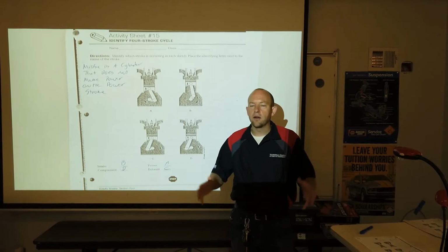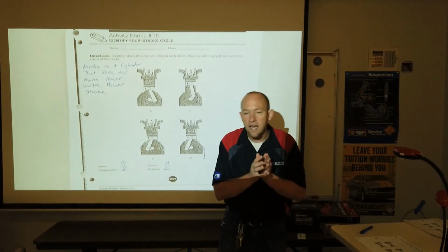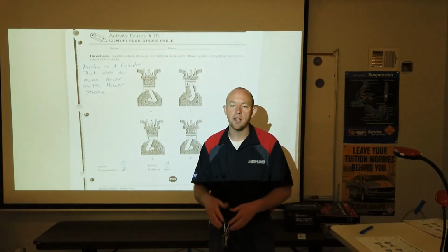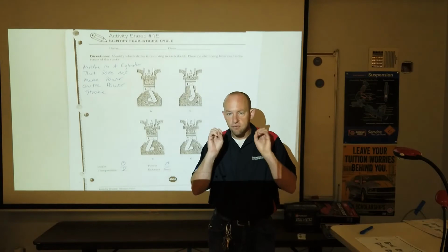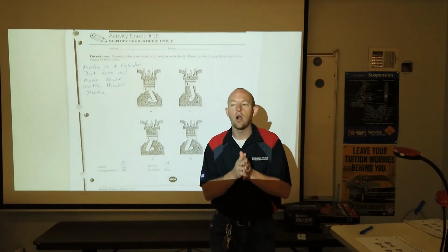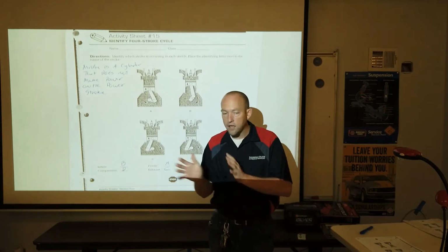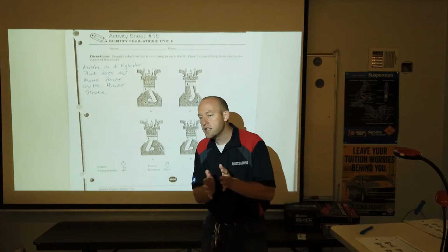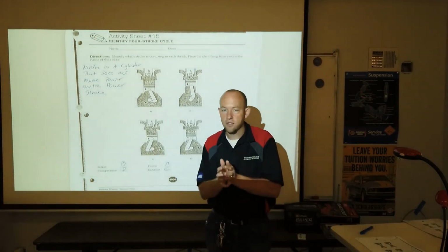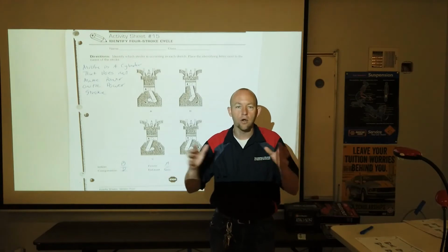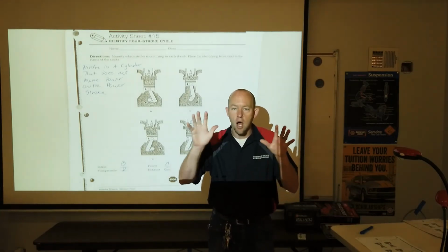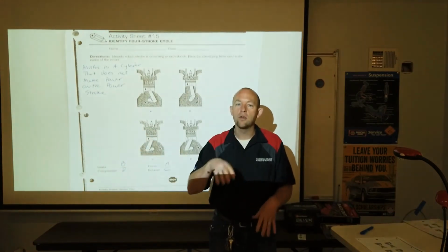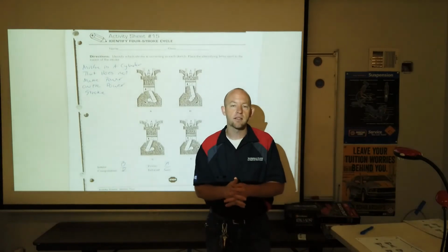That's our definition of a misfire. On modern vehicles, '96 and newer, the computer-controlled system is tracking and looking for misfires, and it'll turn your check engine light on. If you ever have a check engine light that's flashing or blinking at you while you're driving, you should pull your car over and not continue to drive it like that, and fix it immediately, because a misfire would damage an expensive component in your exhaust called the catalytic converter, and so we don't want to drive our cars around with a misfire. A check engine light that comes on is an emissions failure, period. A check engine light that is blinking at you is a catalyst-damaging misfire. That's what that's supposed to indicate.